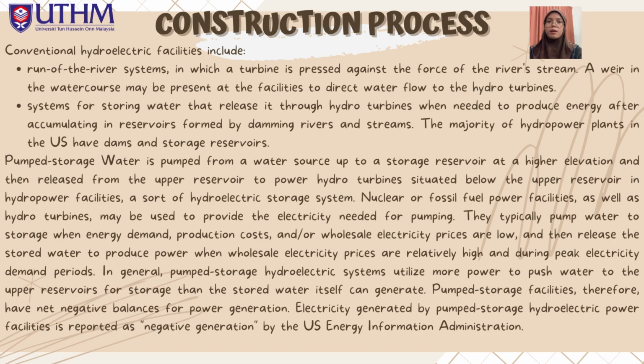In pumped storage, water is pumped from a water source up to a storage reservoir at a higher elevation and then released from the upper reservoir to power hydro turbines situated below it in hydropower facilities, a sort of hydroelectric storage system. Nuclear or fossil fuel power facilities as well as hydro turbines may be used to provide the electricity needed for pumping. They typically pump water to storage when energy demand, production costs, or wholesale electricity prices are low